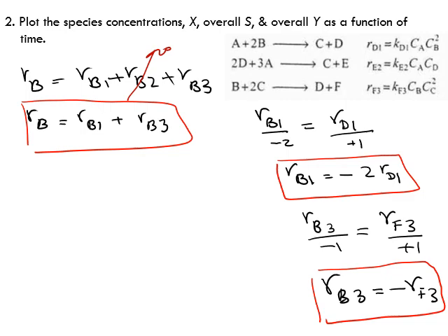Right. Are we done with the stoichiometry? Well, not really. Let's look at the design equation. In the design equation, the right-hand side is dNi by dt. We have the number of moles, correct? And on the left-hand side, we have the reaction rate, which is expressed in terms of concentration, correct? So maybe we need to express the concentration in terms of the number of moles. So that means we have to express, maybe it's better to do it in black.